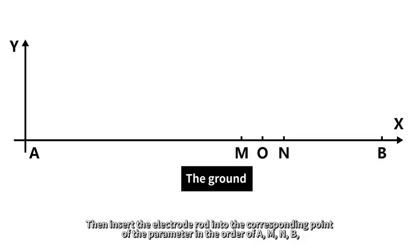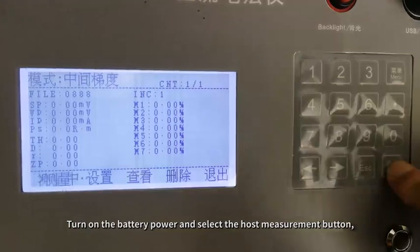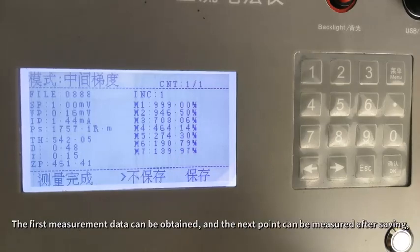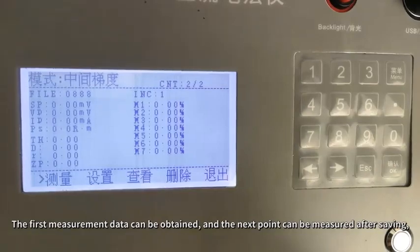Then insert the electrode rods into the corresponding points of the parameters in the order of A, M, and B. Turn on the battery power and select the host measurement button. After the instrument is measured by positive supply, shut down supply, reverse supply, shut down supply, the first measurement data can be obtained, and the next point can be measured after saving.